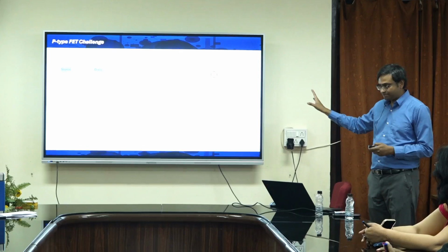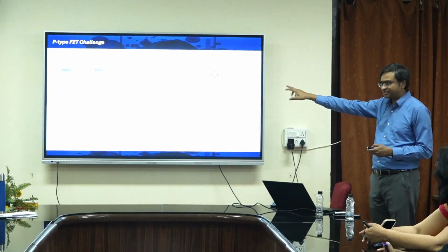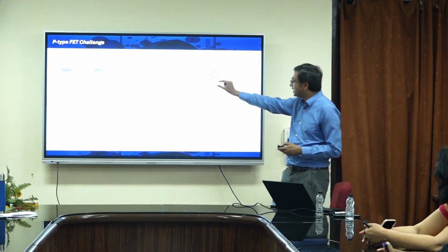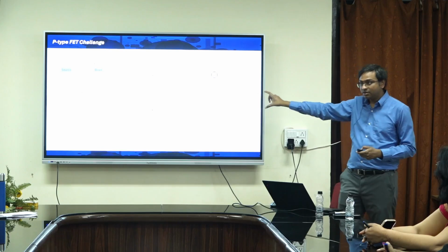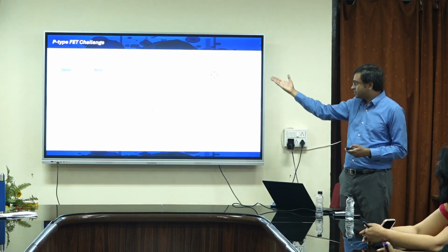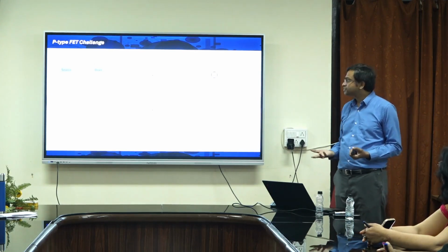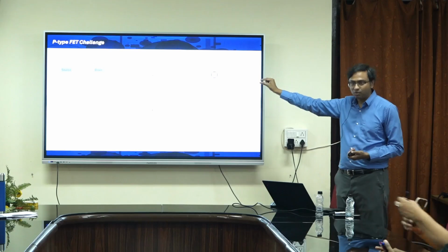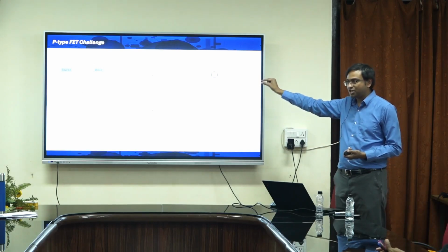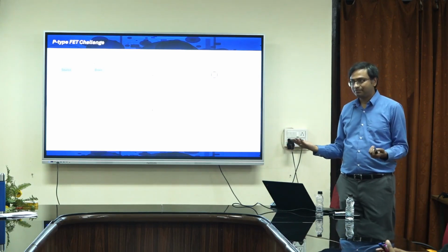WS2 are prime examples. But you see, the Schottky barrier height is kind of small, right? It's not very large. While the Schottky barrier height for the P is very large, because the sum of the two is the band gap, right? And the band gap of MoS2 is 1.8 eV. So if you have a small Schottky barrier height of like 0.1 eV for the electron injection, the Schottky barrier height for the holes is 1.7, right?